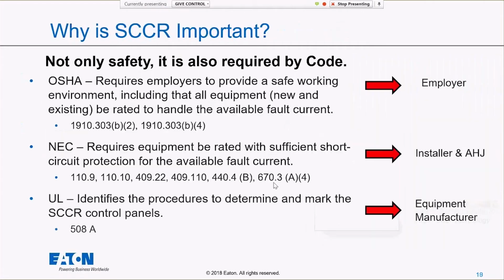So why is SCCR important? First and foremost, safety, right? We saw videos of what happens when we do not have adequate short circuit current rating, and I don't think any of us want to be standing in front of that piece of equipment when it does not have adequate short circuit current rating. So safety, number one.